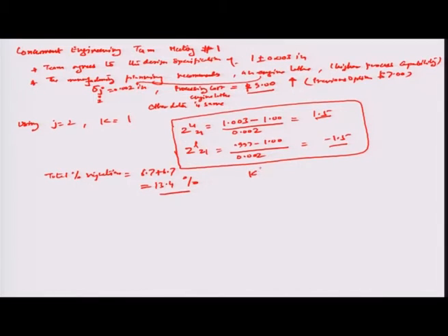So, obviously, the KS21 in this particular case would be 0.1547. Okay, and similarly the KL21 should be equal to 1.1547. You already know this is equal to SCJK divided by 1 minus SCJK. In this case, we are talking about the second machine on the first specification. So, SC21, which is actually this number right here, is 0.134, 13.4 percent.